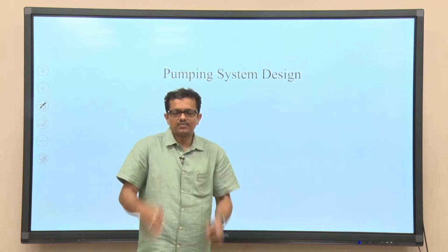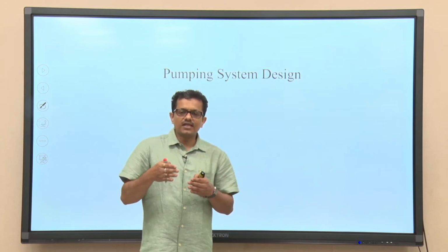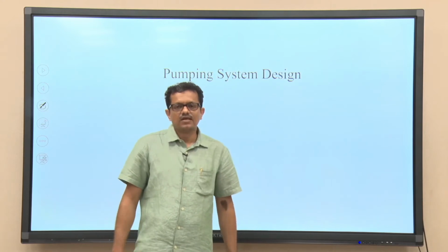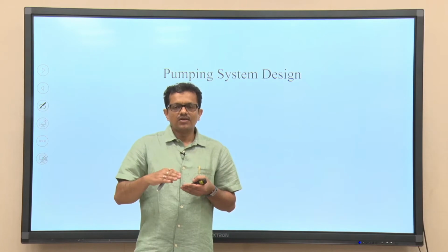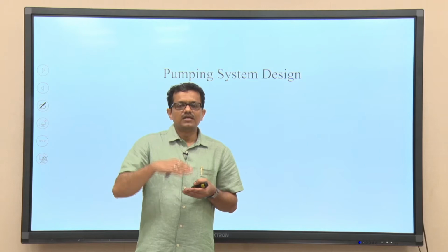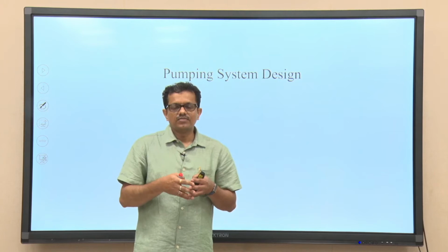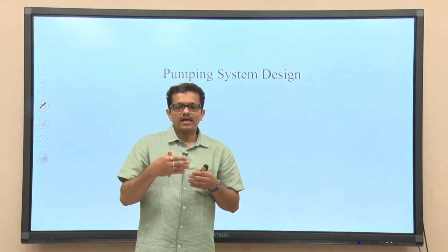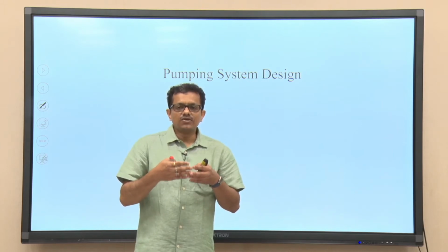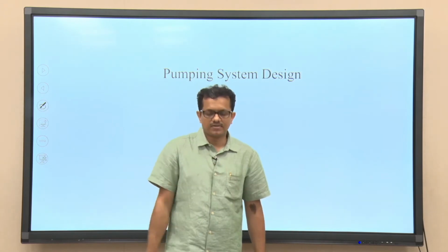If there are multiple pumps installed in a pump house in a given pumping station, we need to know the elevation of the pump house wherein the pump is installed, the elevation of the discharging points, the piping layout, and the number of accessories like valves and fittings, which include bends and elbows, required for the smooth operation of the pump or pumps.